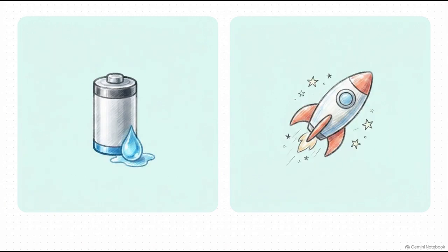But hey, RAM isn't just one single thing. We've actually got two main types here, DRAM and SRAM. Dynamic RAM, or DRAM, is built out of tiny capacitors that actually leak electricity. Because they leak, they have to be constantly recharged, every few milliseconds, just so they can remember their data. I know, it sounds super inefficient, but it requires fewer physical components. That makes it incredibly cheap and allows for really high-density storage. That's exactly why it's used for your main memory.